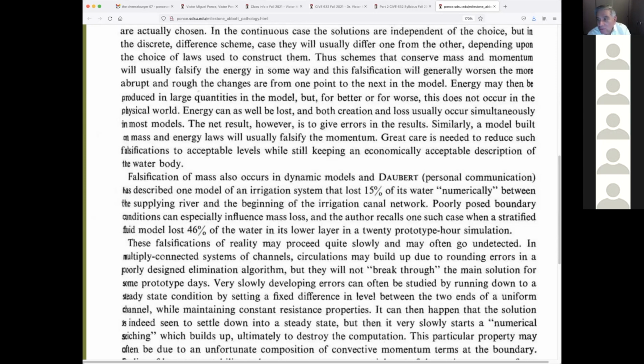So the best thing to do is, if you're developing a model, you have to check mass conservation. And we have shown that in our hydrologic models, the mass conservation is perfect. Every time you write a hydrograph with, like, Muskingum-Cunge linear, it's perfect. The conservation is perfect because it's hydrologic. When it comes to hydraulics, then it's a little more difficult, and therefore you can have problems with the lack of mass conservation. That happens because the more calculations you do, the less accurate the model.